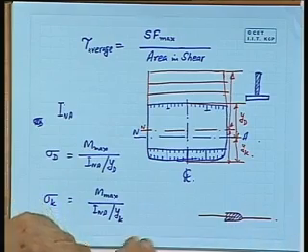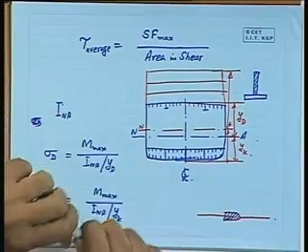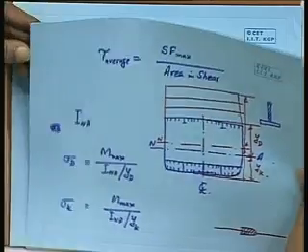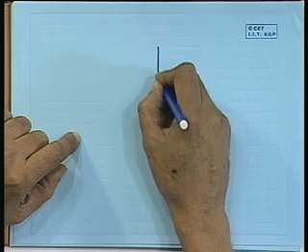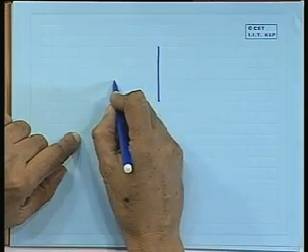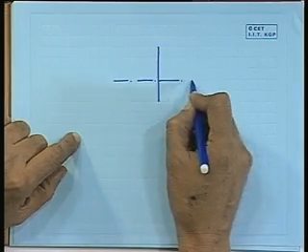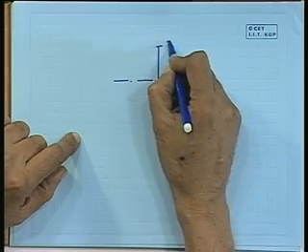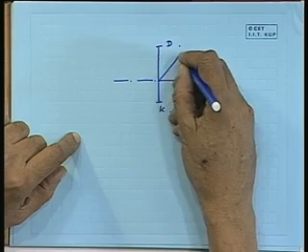So, an expansion joint above the deck level, if you don't want to increase the height. Okay. So this is how we try to change the stress. Now, if this is the case, then how will the stress vary? If we take the section here and say that this is the neutral axis, this is the keel point K, this is the deck point D, the stress varies something like this.